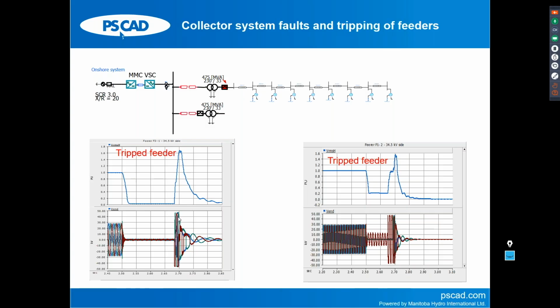In this case, the left-hand side response may or may not be acceptable. The voltage goes up to about 1.66. It lasts for a few tens of milliseconds. It may violate temporary overvoltage, withstand capability of surge arresters and equipment, and damage equipment.